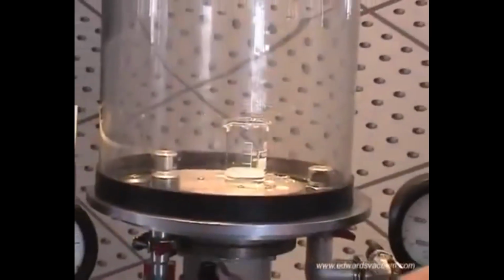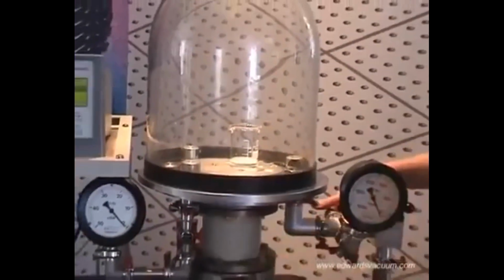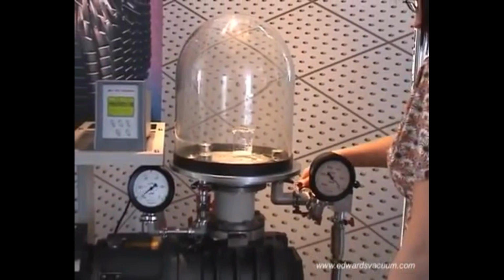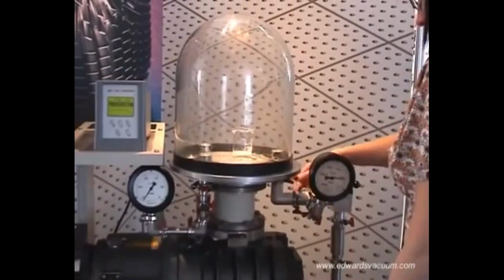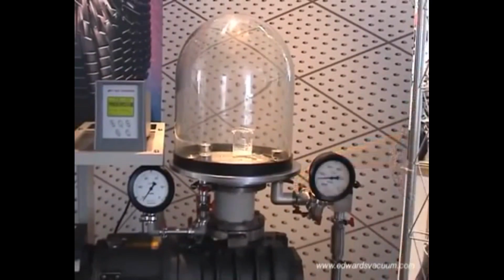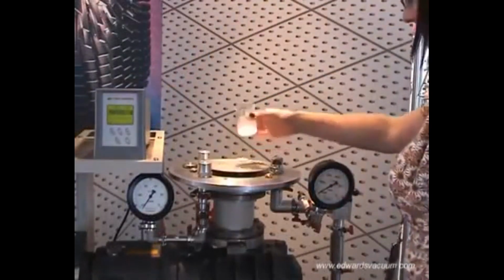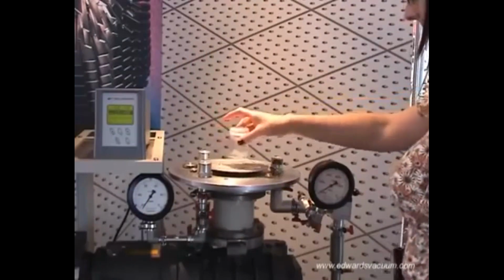In this demonstration, we don't add any heat, but instead reduce the pressure. When this pressure is equal to the water vapor pressure, the water boils or changes phase, but at a much lower temperature. In fact, the energy for boiling is coming from the water, and consequently its temperature reduces, and as the pressure becomes lower, the water will eventually freeze.